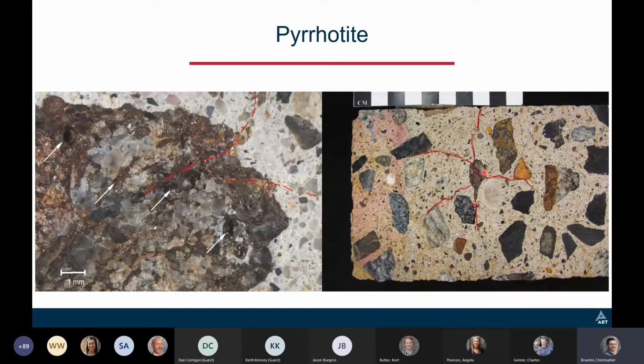This is a better visual. It actually started to create radial cracking around the single aggregate particle. Now, this is more of a big deal right now on the East Coast of the United States and up in Canada. I believe they might have even had problems first up in Quebec. And then in America, it was Connecticut where they really started to experience these problems with pyrrhotite. They had all these housing foundations made out of concrete, and they started to crack and kind of fall apart.